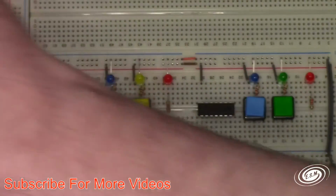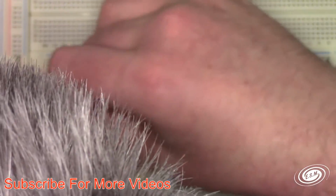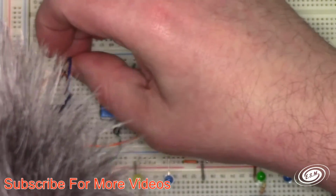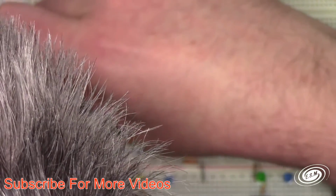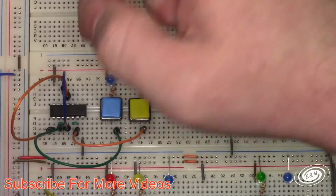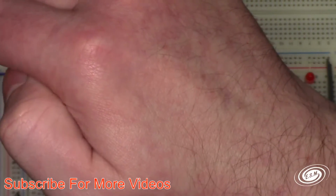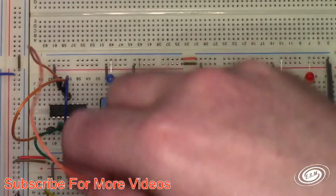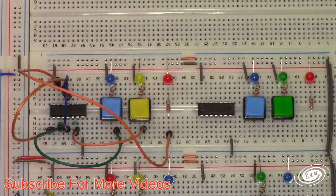Then I'm going to take the input from the B input, that NOR gate, and I'm going to tie it to 12 because that is my second input to the third NOR gate. And then I'm going to take my output of that one, so pin 13, to my output LED, which is red. So this should be an AND gate.